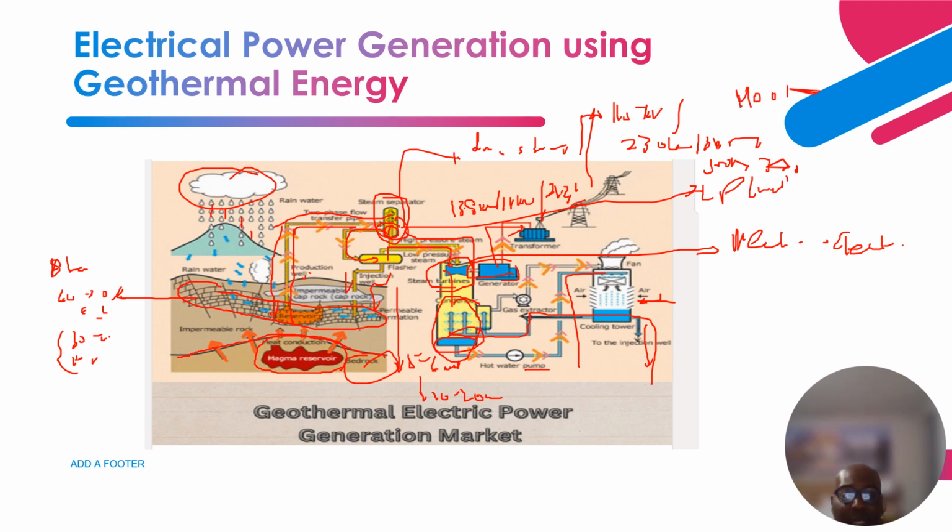Basically it goes into the transmission system. This is the high voltage transmission system, because it travels for thousands of miles before it gets into a sub-transmission substation, where the voltage is stepped down, because the goal is to achieve distribution voltages. So it has to go through sub-transmission, then from sub-transmission go into distribution substations.